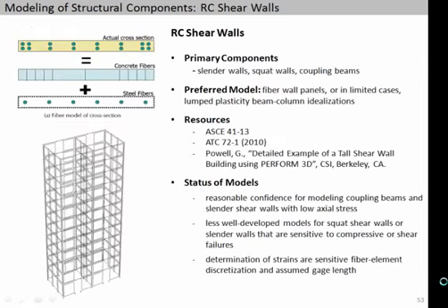So moving on to concrete shear walls, and these are probably most important because so many of the buildings are built with these. The most popular models to capture these are fiber type models. This is not one fiber element coming up from the base, but actually panels of fiber elements put together, where basically you're modeling the uniaxial stress-strain of steel and concrete, say the concrete modified for confinement.